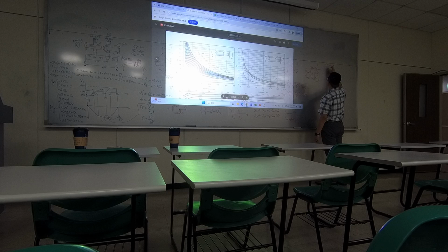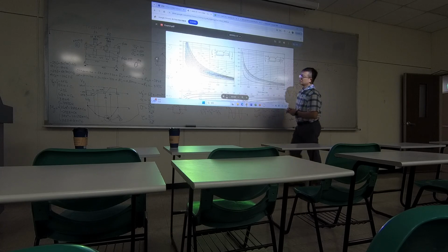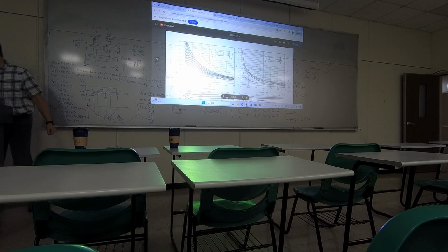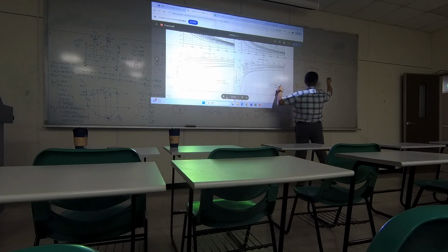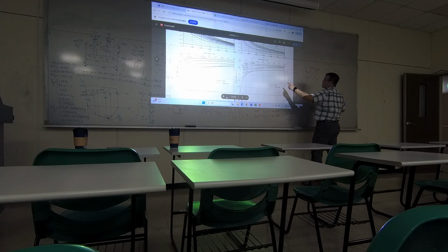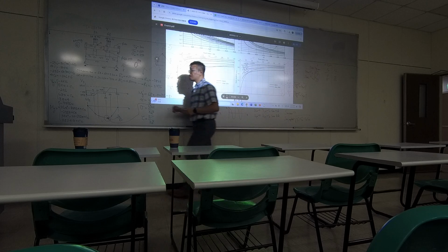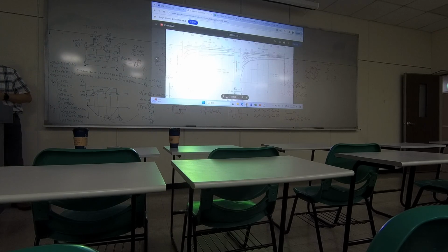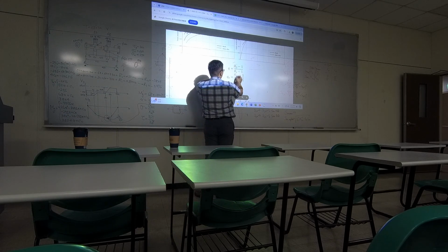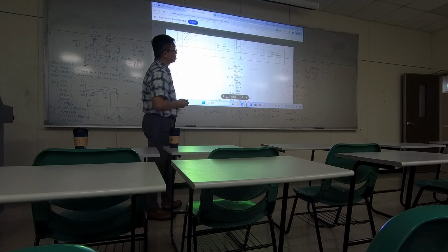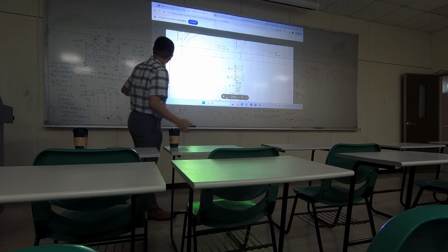The figure on the left upper corner gives you Kt. The one on the right gives you Kts. And then use the 2 figures at the bottom. That gives you Q and Qs. Okay? Q and Qs. And using the 2 equations I gave you, you can compute Kf and Kfs. So the entire solution process is like this.